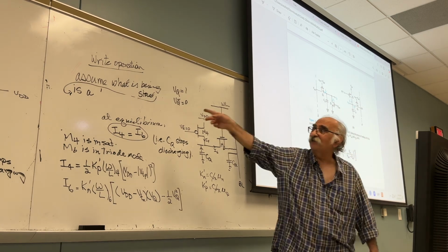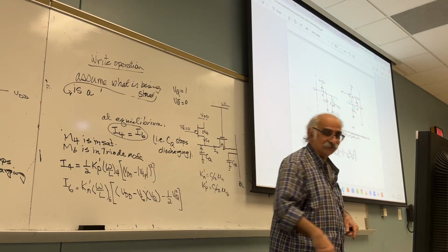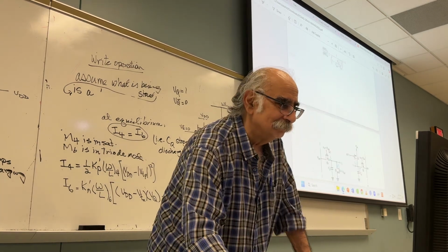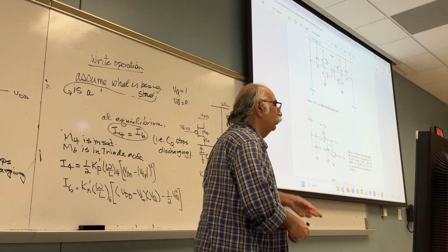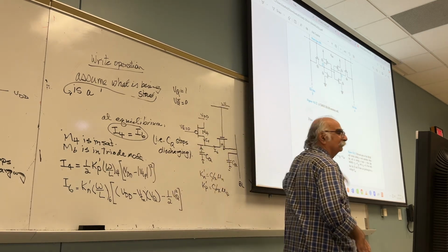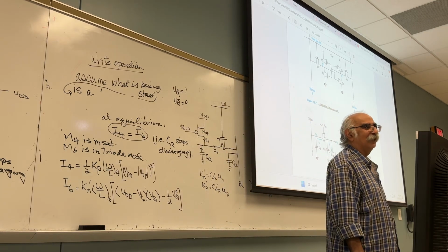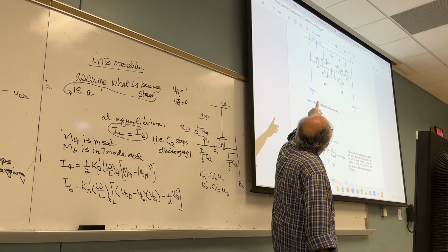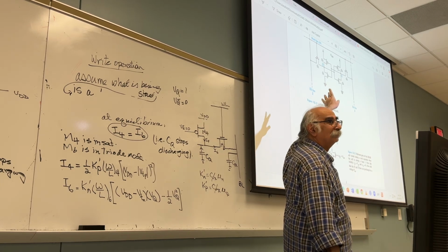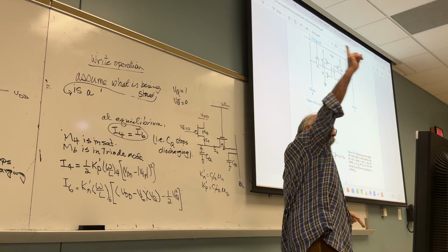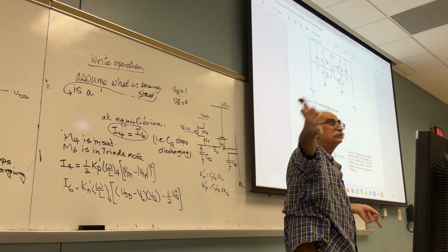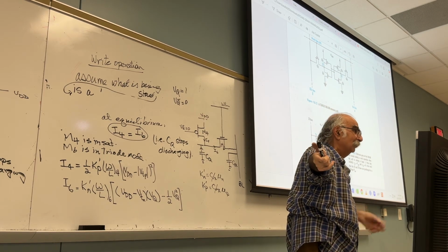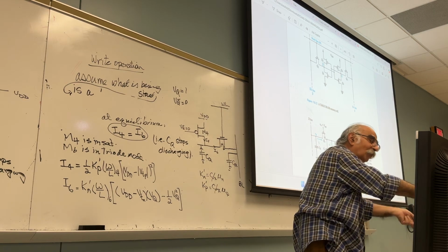Which transistor? M2. Is it a switch? What is the Q bar? Q bar will go to 1, which means the Q will go to 0, which means you have written a 0.